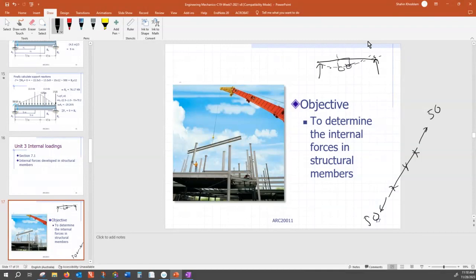So you have to answer this question. When a truck is passing over a bridge, yes, we know how to find the reactions. That's not good enough. We have to find at each individual point what forces are developing inside, because those forces eventually can make my bridge break. My bridge can break here, here, or here. For every bridge, that failure point or critical point is different. So you have to do a customized solution for every bridge, for every beam. Why? Because you want to know which point is the most critical point.